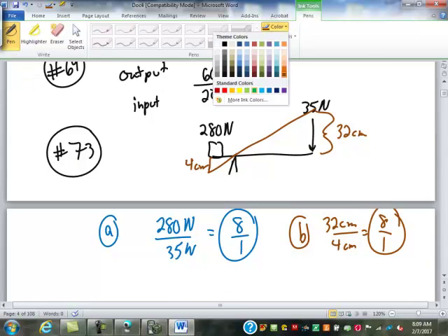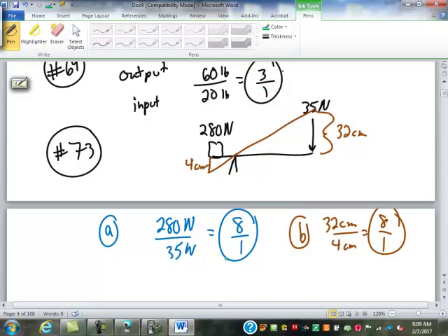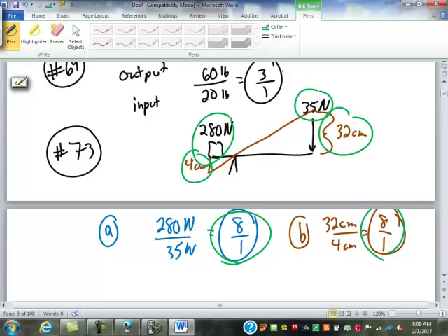What do you notice is the relationship between the ratios? They're the same ratio. When you use a lever, in fact, most simple machines, a pulley, a lever, a wedge, a corkscrew, you can lift stuff that's heavier than the force you put in. The trade-off is distance. Here, we're ignoring friction. You can lift a weight that's 8 times heavier than the force you apply to it. The trade-off is you have to move 8 times as far as what that weight's going to move. So if you want to lift it a foot, you've got to be able to move 8 feet.